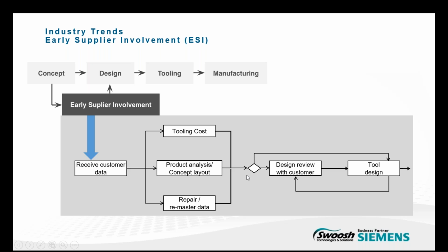Now, you're probably familiar with this diagram. Essentially, the first step in the process is for the mold manufacturers to receive data, commonly referred to as a database, from their customer. This database can include STEP or IGES files. Sometimes the data arrives in a native CAD format and must be translated. Once that's obtained, it's then analyzed for data quality, moldability, and part properties.